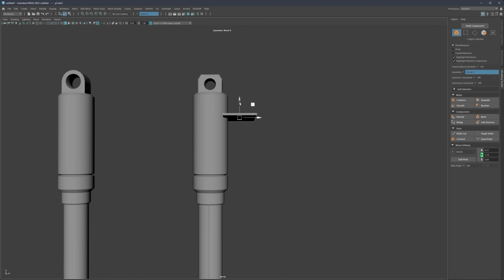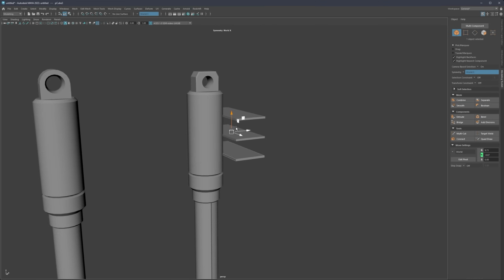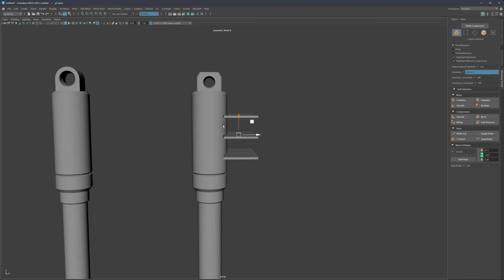While in move mode, let's hold shift, and then let's clone it once. And then I'm going to hit Shift D to clone it one more time, and then we're going to get the same distance. So let me repeat that one more time. If I create one distance here and hit Shift D, then you will create 1 extra distance there.